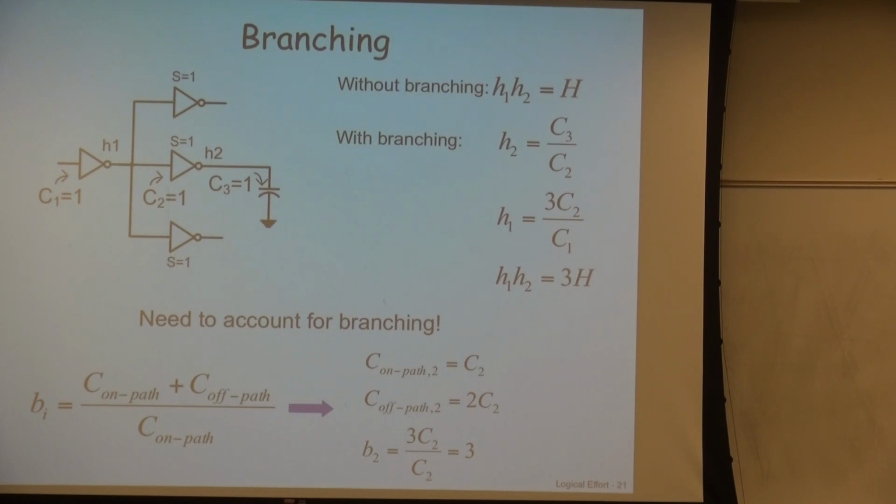Because if your clock frequency is higher than that, then this is not going to be computing correctly. Now, just because you have other stages smaller and one stage big, you cannot say that, okay, I will just increase the clock frequency a little bit, right? Because then your computation will be wrong. So that's why in any system design, first and foremost, you have to find out what is the critical path.